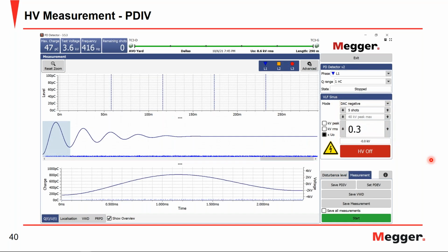So we move forward, and I just started my measurement. Again, we want to start at a low voltage, so I started at 0.3 times our RMS voltage, and I did multiple excitations. If you look at the IEEE standard for damped AC testing, they recommend to step up in voltage and to have multiple shots or excitations.